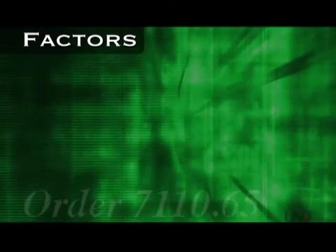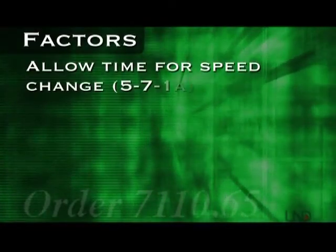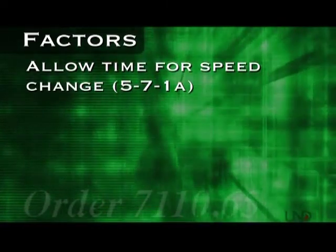The 7110 lists some factors to keep in mind when issuing speed adjustments. First, aircraft do not speed up or slow down on a dime. So understand that when you tell an airplane to slow down or speed up, it may take a few moments to reach the new speed.